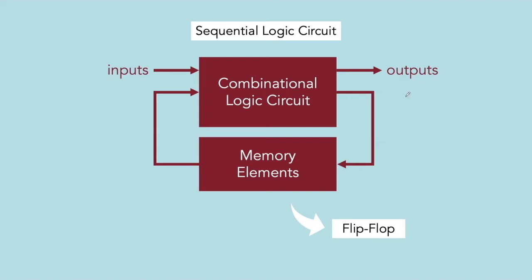These devices are called latch and flip-flops. The subtle difference between a latch, not shown in this diagram, and flip-flop is that a latch is level triggered and a flip-flop is edge triggered. But for practical purposes, we will just focus on flip-flops and even consider flip-flop versions of some latches. For example, if we have an SR latch, we will just explore its flip-flop version, which is the direct coupled RS flip-flop, etc.